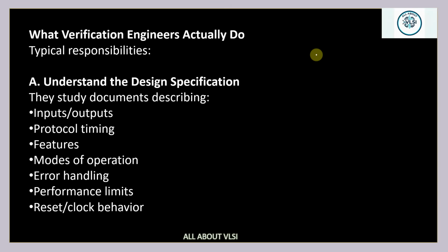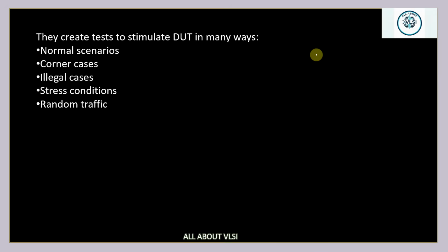You first need a good understanding of how UART works, how SPI works, how the design is converting UART to SPI, what mechanism it uses, how it latches, and the timing related things. You need a good understanding of those things, and then you start with the verifying.